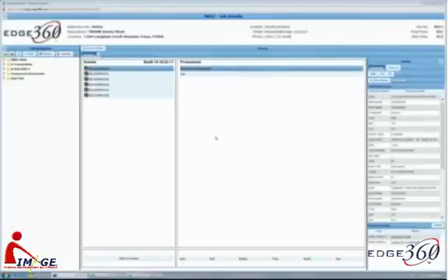We draw the P&IDs in CADWorks P&ID. We use our tools to link the P&ID and 3D models, and then we publish them with our publisher, which takes what AutoCAD does with making DWFs, but then we hang a lot of information in the form of hyperlinks and others into those documents, whereby when they're placed into the Edge 360 cloud space, Edge 360 knows how to interpret all of these things to maneuver back and forth.